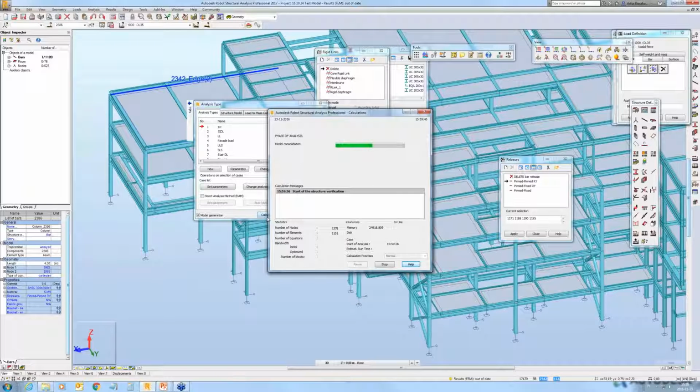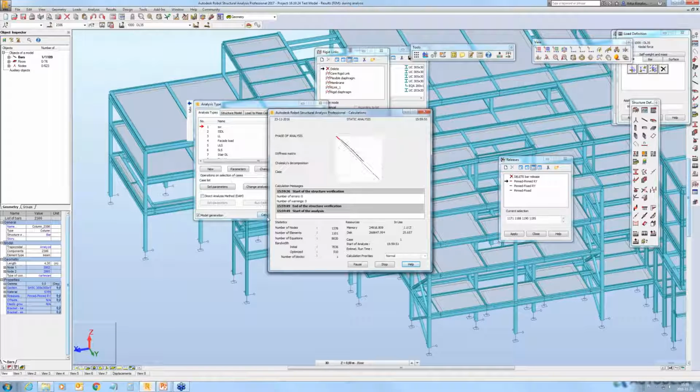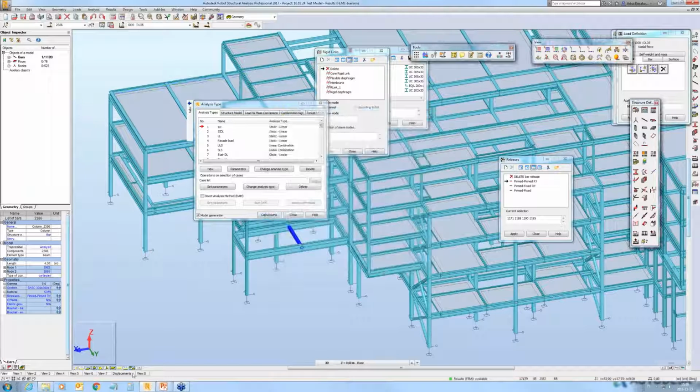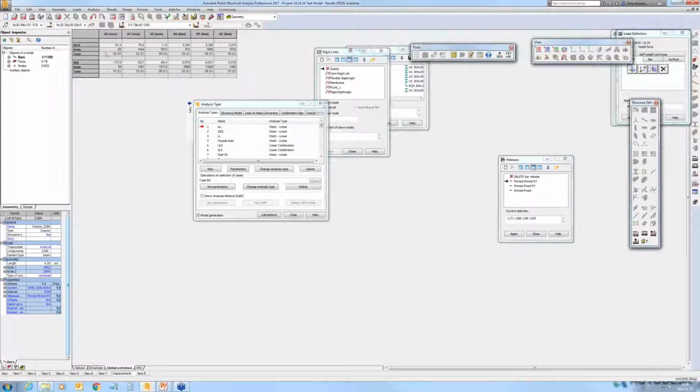After deleting the releases, the calculation time for Skyline solver should be much faster because of the better conditioned stiffness matrix, and we have no instability reported. And we may see that there is an increase of the horizontal displacement, but this is as expected. So now we may say, okay, we solved the problem, and when we restore rigid links, we can ignore the instabilities. So okay, let's go back to the presentation.